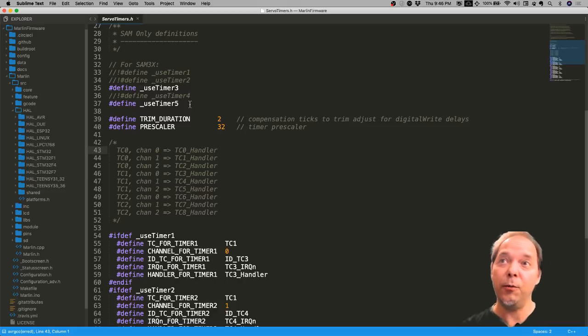And that also matters for 32-bit. We're using fast I/O even for 32-bit for most cases, although a lot of them do actually just use digital write and digital read as their pass-throughs. So with 32-bit, the theory is it doesn't matter because they're so damn fast. So, in some sense, I agree. If the code that leads up to just calling digital write itself is smaller, and the code that runs in the background might be a little slower, you still get smaller code, and that can sometimes help performance because less reading of code is actually part of the equation.